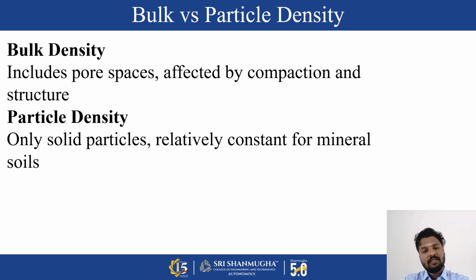While calculating the bulk density, we include the pore spaces in the measurement or calculation. But in the particle density determination, we exclude the pore spaces and include only the solid particles to find out the particle density. So bulk density is affected by compaction and structure, but at the same time particle density is relatively constant for mineral soils. Okay, we can move to the next slide.